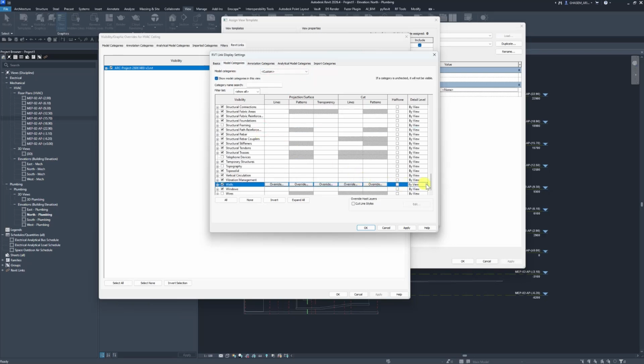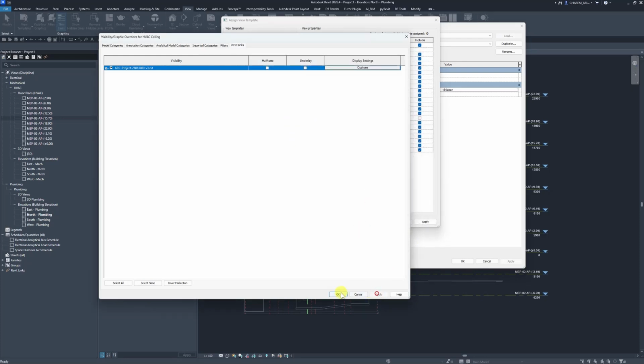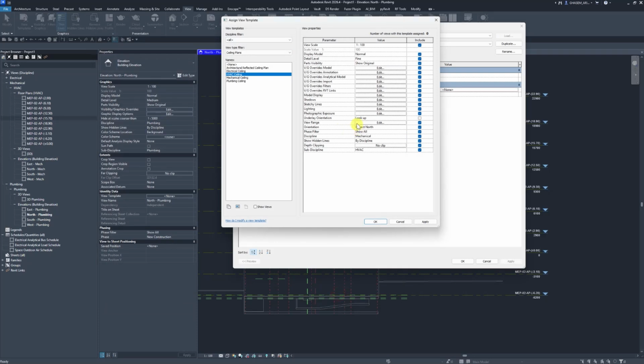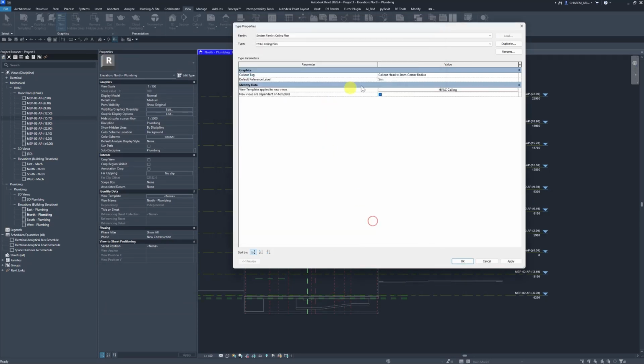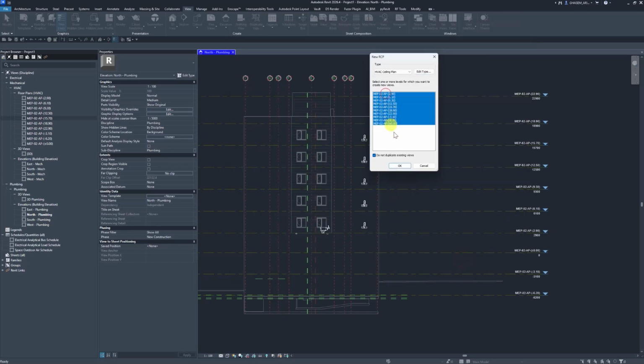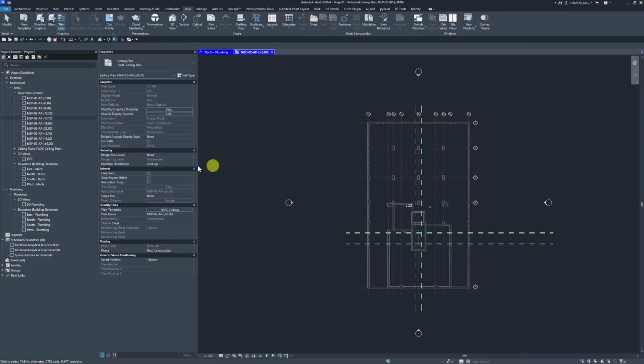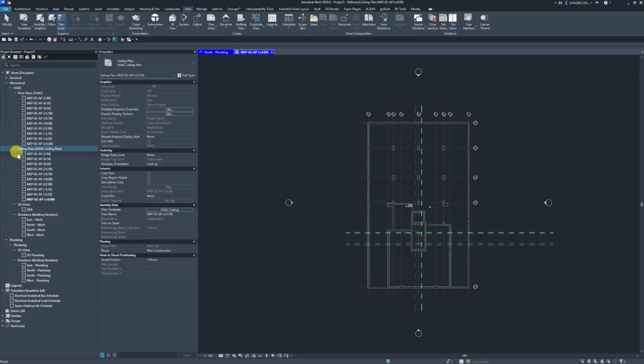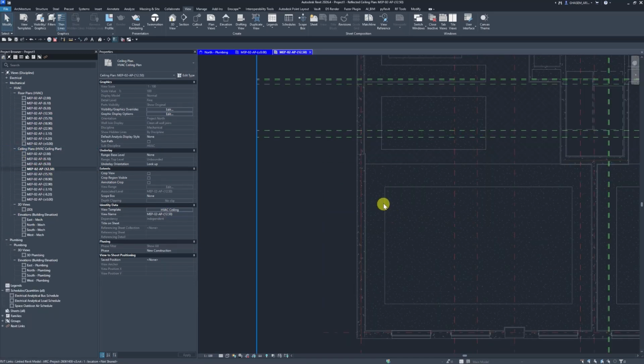Here we need to set the detail level for walls on coarse. Or any other elements. We talked about this. All right, apply and OK. Everything seems fine. Back here, select the levels. And hit OK again. And basically, now we got the ceiling levels in our project browser as well. So we can easily check them out.